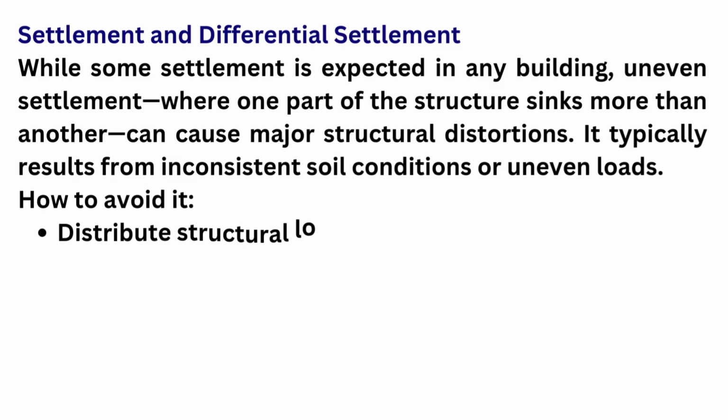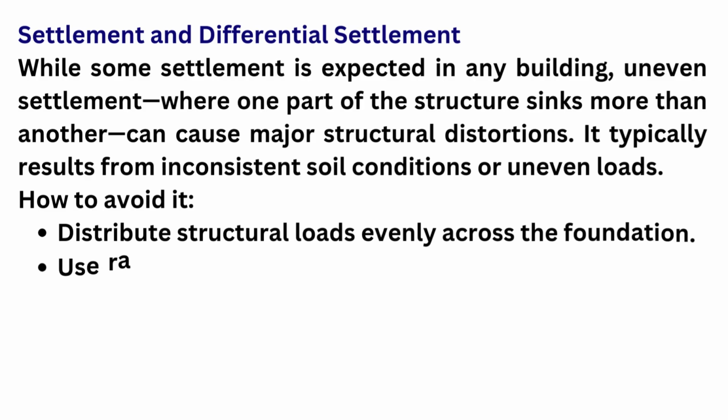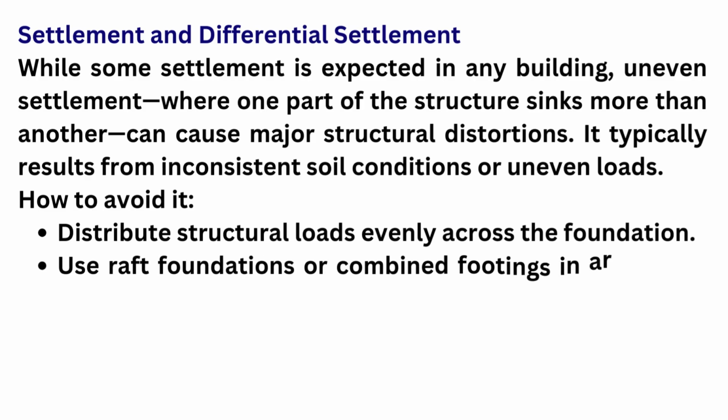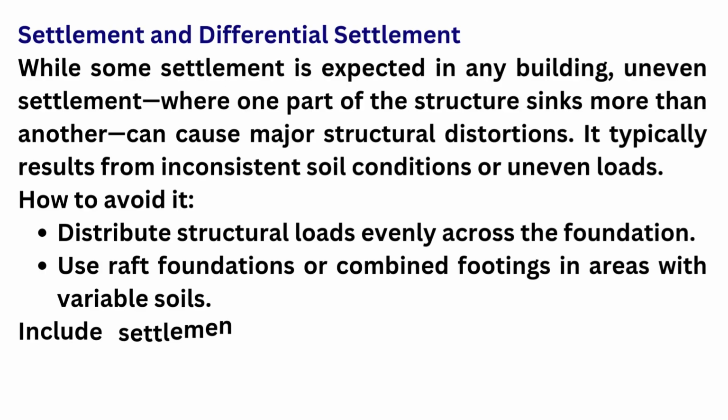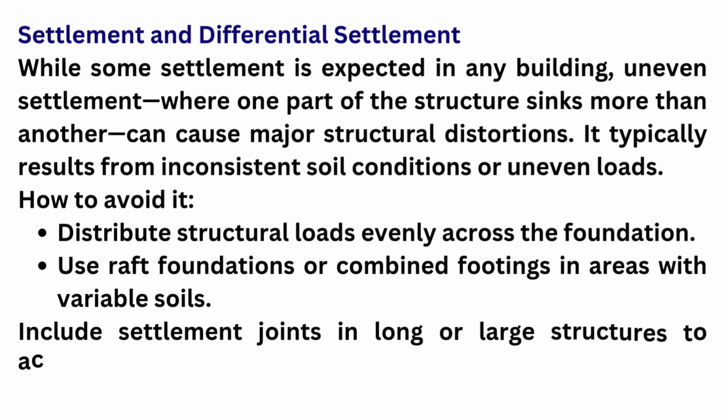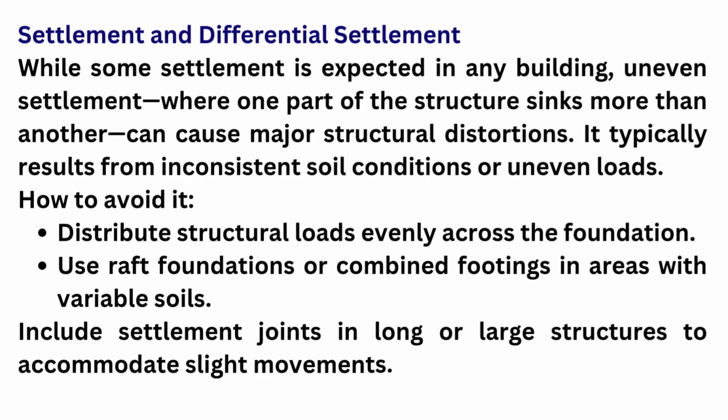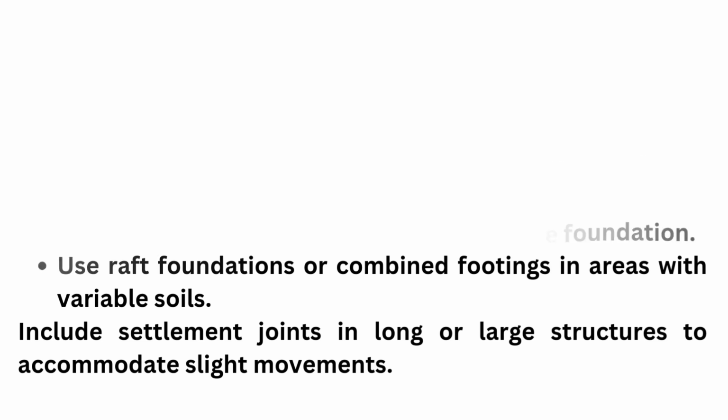How to avoid it. Distribute structural loads evenly across the foundation. Use raft foundations or combined footings in areas with variable soils. Include settlement joints in long or large structures to accommodate slight movements.